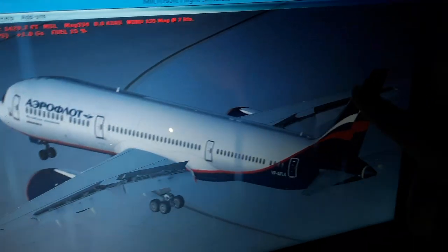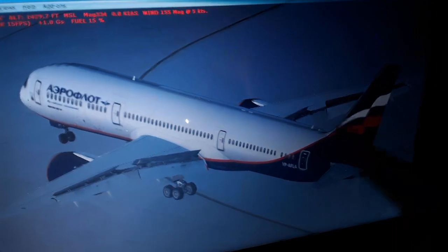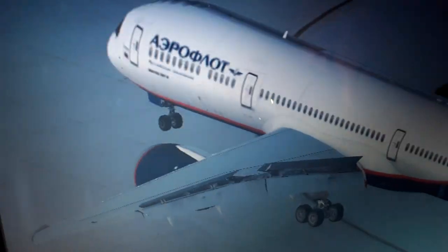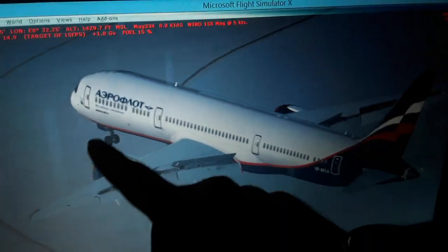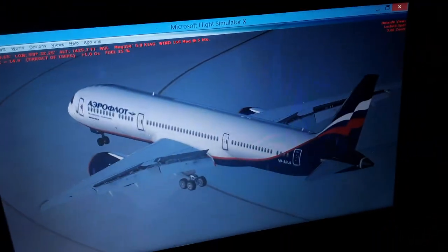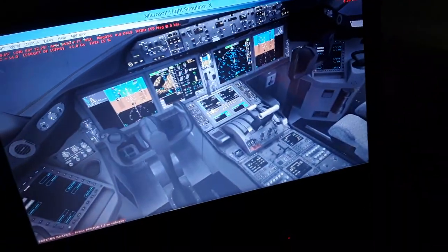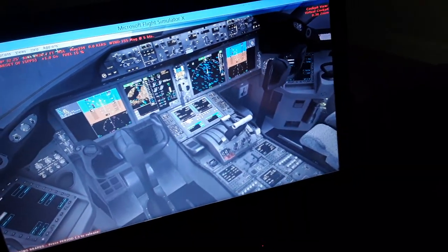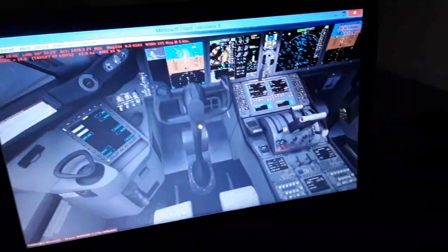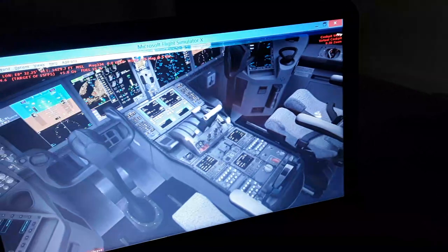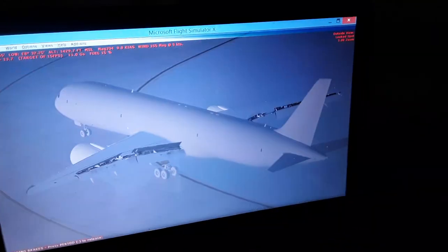When we reach 45 knots or 72 kilometers an hour, the forward nose wheel deflection is limited by the computer automatically to 7.6 degrees. So we use the rudder pedals, as you can see, to input left and right turns from the nose wheel or the rudder when we are in the air. We also have the tiller for the left and the right, captain and first officer side.